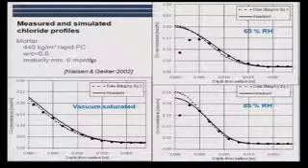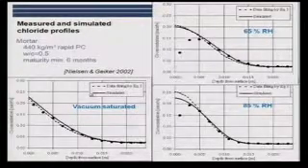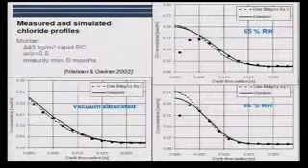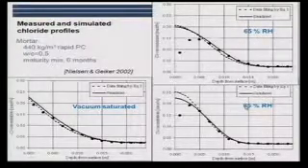That means that during the testing, we don't expect much change. That was why. And we saturated the samples or conditioned them in different ways. One was vacuum saturated, one stored in 65% relative humidity, and one in 85% relative humidity.